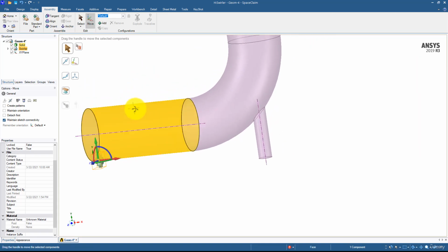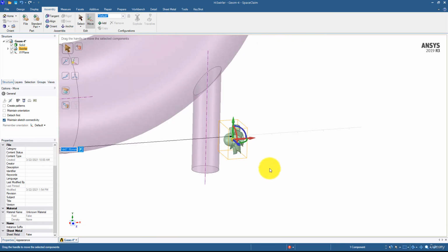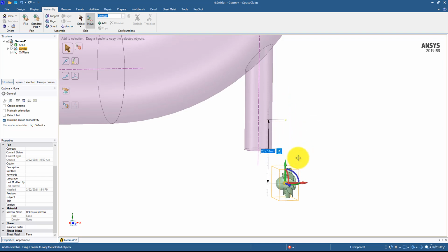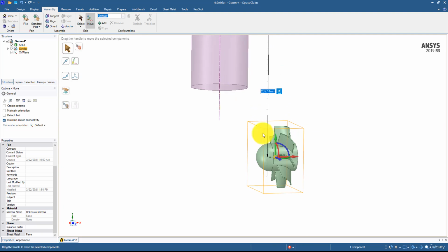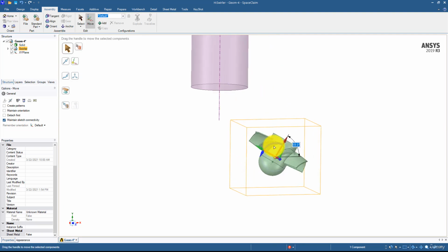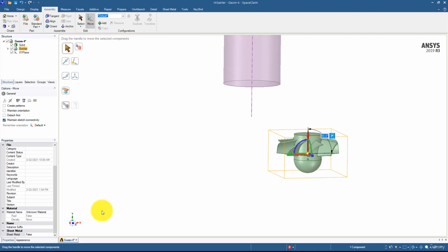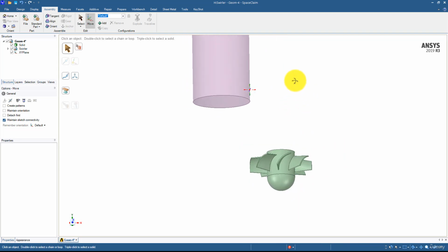This will open this geometry in the mixing elbow model. Slightly move this geometry towards the small pipe, and also on the downward side. I also want this side to be facing the flow from the small pipe, so I will move the geometry by 90 degrees in the Z direction, or this is the Y direction in fact.